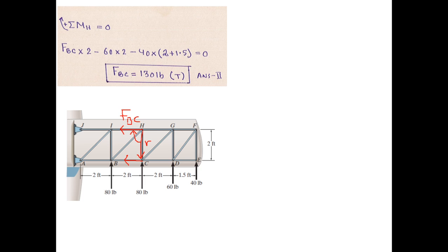So this is a very simple trick and a step that you can use if you are stuck in calculating the rotational sense of a moment. You just need to join the tails of the two vectors, and you have to make sure that you do not change the orientation of the force. So if it is in this direction, you have to preserve this direction and just join the tails, and then make a curl starting from the moment arm vector R and ending at the line of action of the force, and this will give the direction of the rotational sense of the moment.